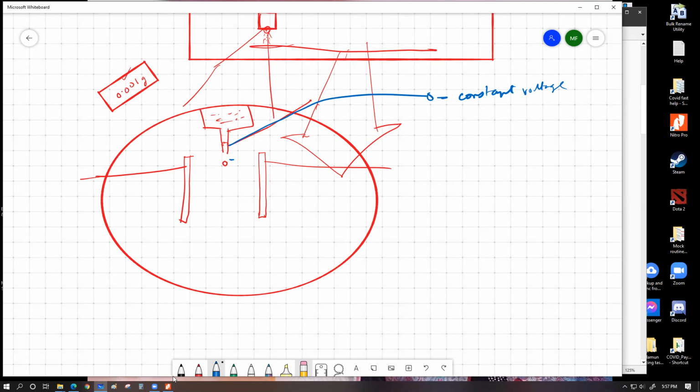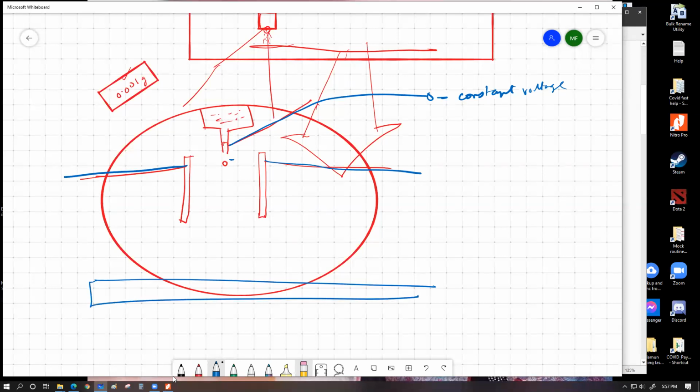Because we're going to control the movement of this ink droplet by controlling the voltage across these two metal plates. So this is a metal plate connection, this is another metal plate connection, and underneath, in a very highly magnified version, let's say this is a piece of paper. I'm drawing this piece of paper like a block because this is highly magnified, so this is the thickness of the paper. Paper is actually pretty big.